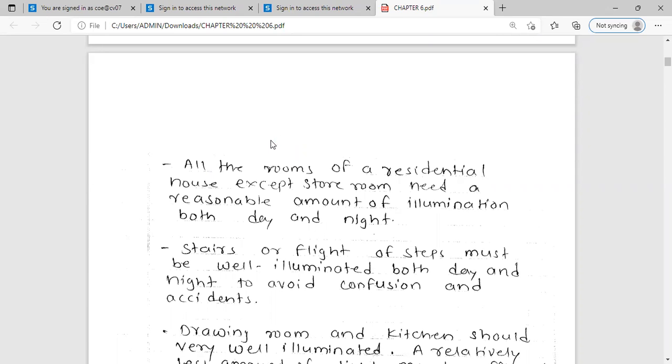Generally in a kitchen we are preparing the meal, at morning time and night time. At morning time, whenever we are preparing the meal, more heat gets generated. For the remaining time of the day, the kitchen room should be kept cool. For that purpose we go for the provision of the kitchen room towards the eastern direction or eastern aspect.